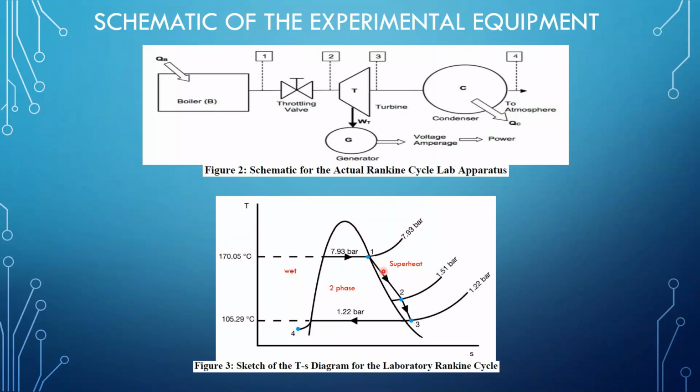Now to the right of this main graph, we have the superheated region, right? Now this is the typical shape of these TS diagrams. And this point, the apex of this graph, is usually called the critical point. Now this line to the right of the critical point is often referred to as the saturated vapor line, and to the left of the critical point is the saturated liquid line, right? Now that's important to remember.